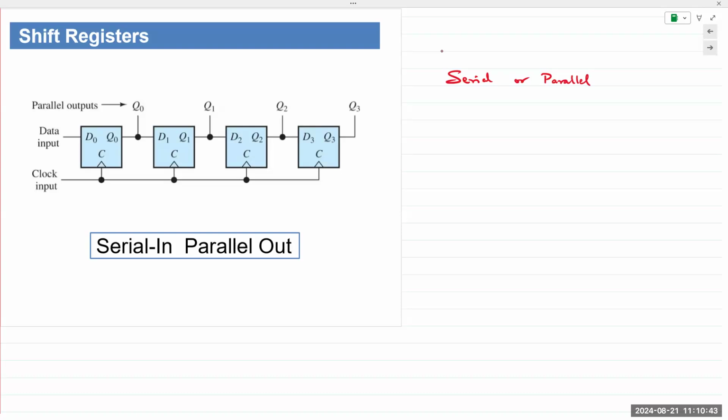So if you want a 4-bit data transfer, then you need a 4-bit shift register. 8-bit, 32-bit, 64-bit. So all in parallel, you need that many shift registers, which in a normal system nowadays is basically nothing. Serial and parallel again indicate the mode of transfer of the information. Serial is more efficient in the sense that it requires just a single data line.